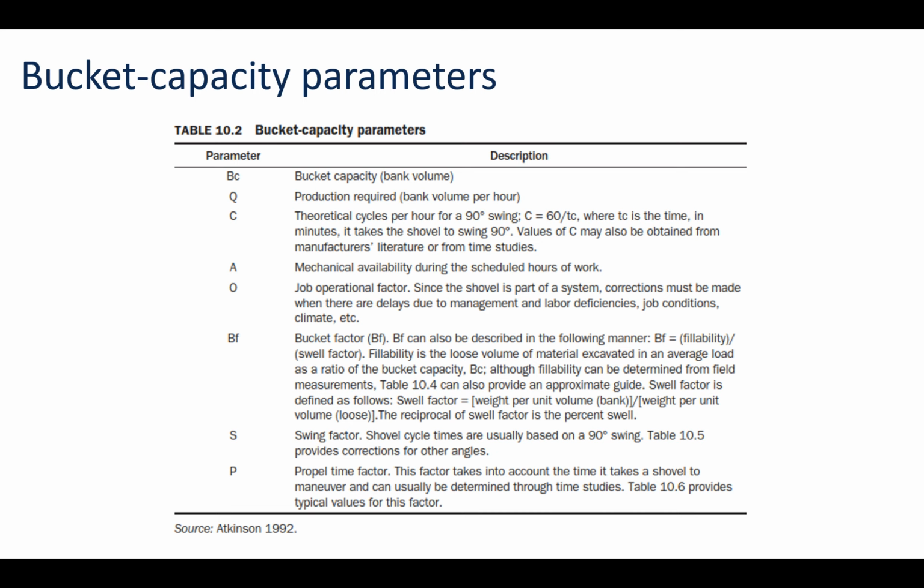Swing factor, so we usually are determining this based on a 90-degree swing for a shovel at least. It could be less, it could be more, but you don't want to get too far off that. Otherwise, you're trying to load in a less than ideal situation.